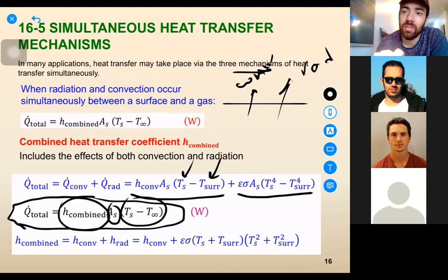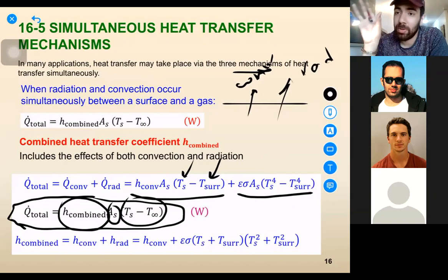And also we had a constant before them. For example, conduction, you had K. In convection, you had H. And for the radiation, you had the emissivity term and the Stefan-Boltzmann constant. The only difference was that the temperature difference term was the subtraction of the fourth power of those temperatures from each other.